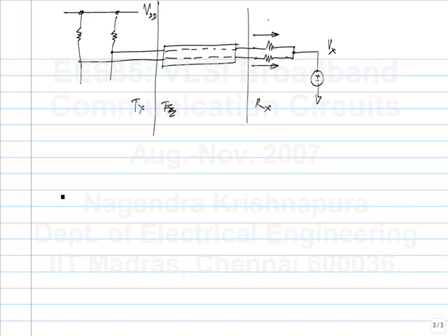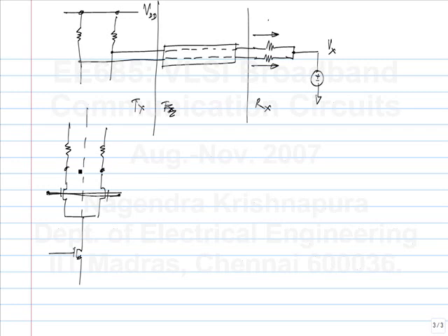So essentially, are you guys all familiar with common mode and differential pictures? Yes or no? You make the common mode equivalent circuit by, let's say you have a differential circuit and you have a line of symmetry. Common mode by definition means all the differential inputs of the differential circuit are tied together, to the same voltage. So I tie these two together, and because of circuit symmetry, these two will also be at the same voltage. So I can actually connect these two.